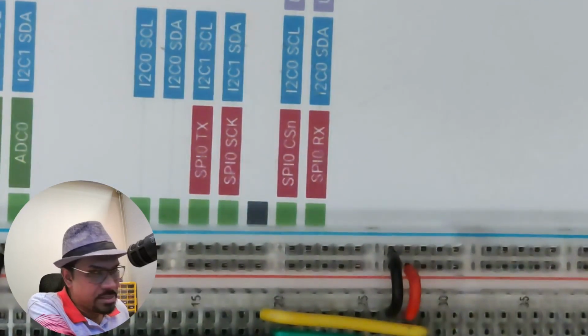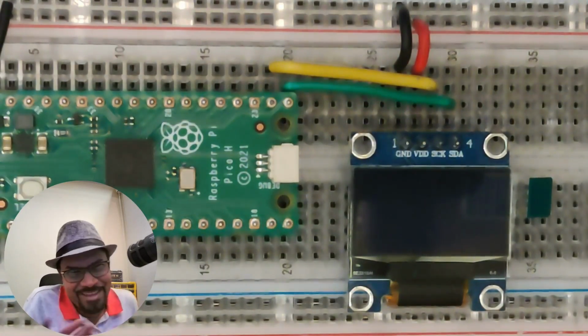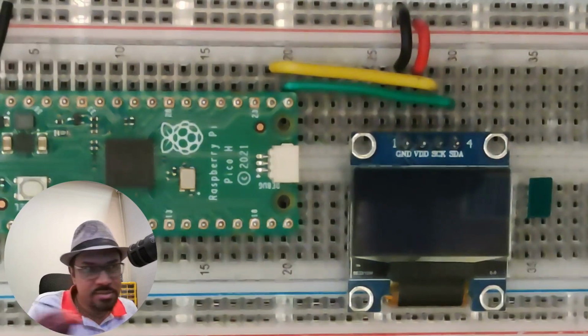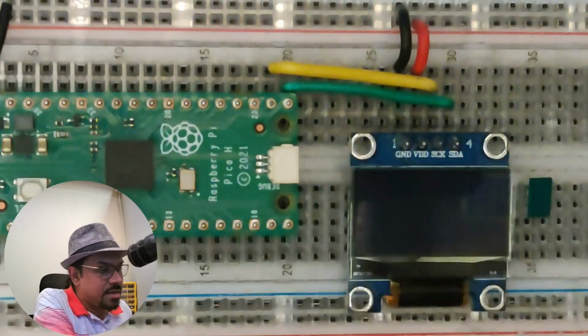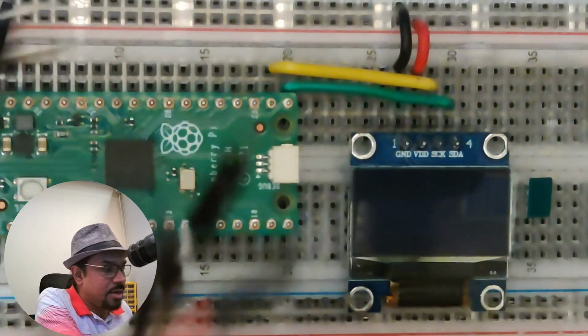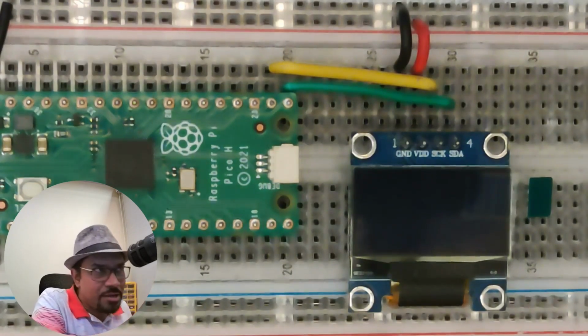So you just have 2 pins from here connected to this and so on. By the way, for simple connections like these, using a breadboard can be avoided. You can use jumper wires like these, right? This is a male-to-male jumper wire, but because both of these have headers, you might want to use a female-to-female jumper wire to connect them across. So you don't even need a breadboard.